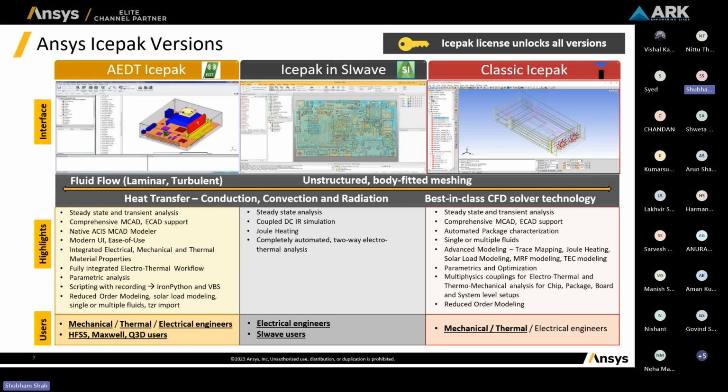When it comes to any CFD simulation, or anything related to CFD simulation, turbulence plays an important role. A number of turbulence models are available, whether the flow is laminar or turbulent. All the models are available both in AEDT as well as in Icepak Classic. These are a few highlights of which kind of simulation you can use in which tool.